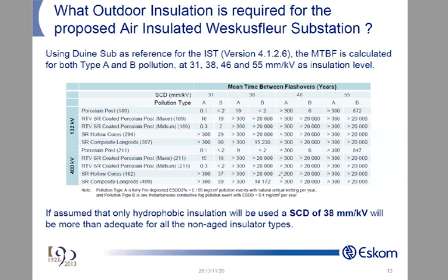But now the actual coating is covering like a little blanket. Now remember, it took long for it to get in. It's also taking a long time to get out. So your porcelain insulator now is hotter than a composite next to it. So now what happens is, for dew to form on that RTV coated porcelain is more difficult than it is on the normal bare silicon one, because of this temperature retaining.